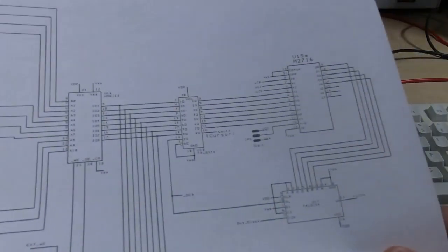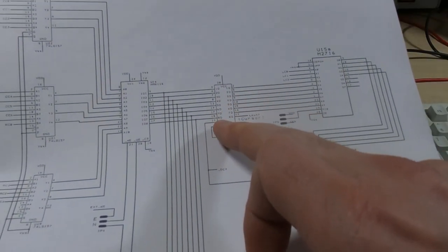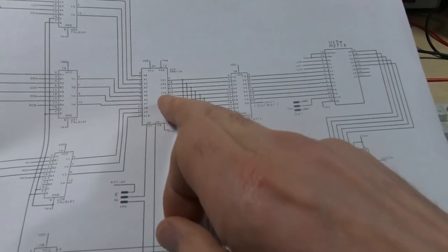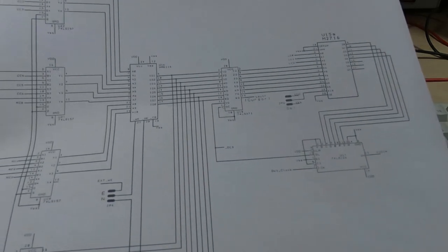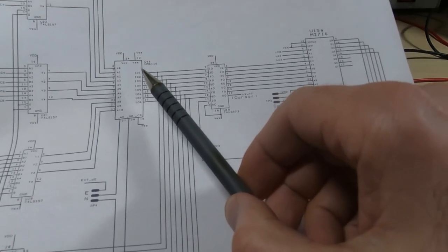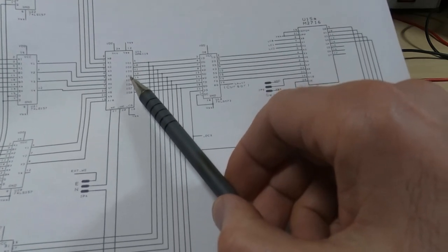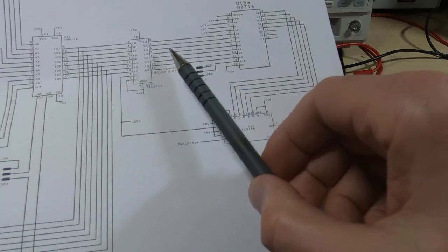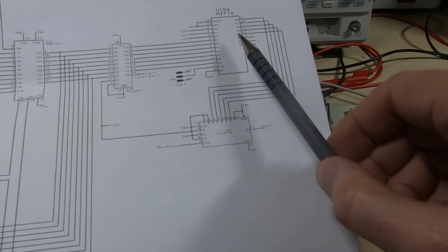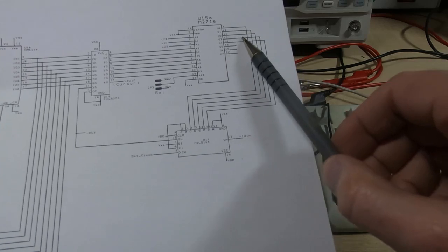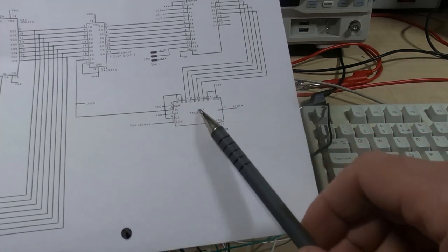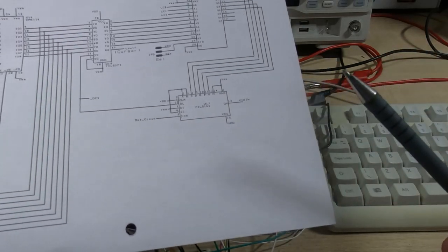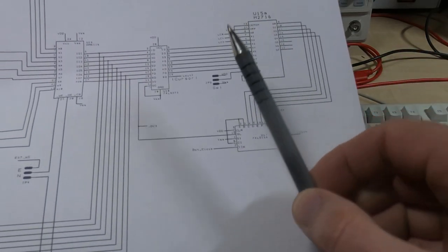So as I said, it's this buffer here, and the reason we need this is because of the way this system works. We have the SRAM here that holds the video data, the character data of which particular characters we want in which particular position, and that data is sent through to the character ROM, and the character ROM then selects the particular part of the character bitmap depending which row of the character is being displayed.